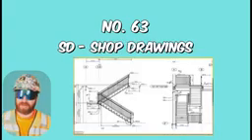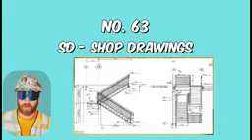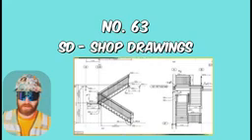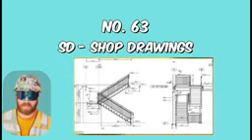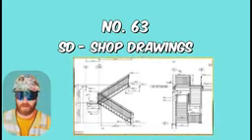Shop drawings, which is another submittal, but the shop drawings are actually drawn by the installing contractor or manufacturer, and it expands on the details that may not be shown as in depth in the construction documents. Again, it's to show intent of the design, and it gets reviewed by the architect or engineer on record.